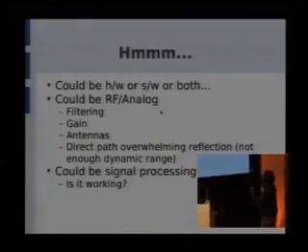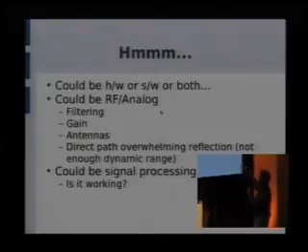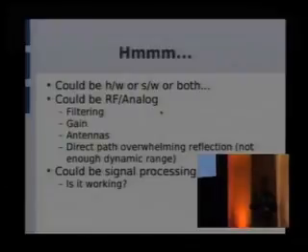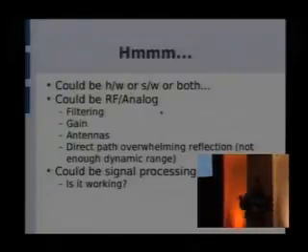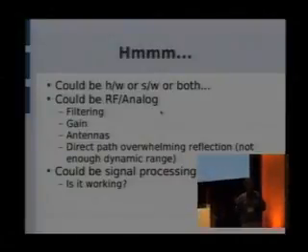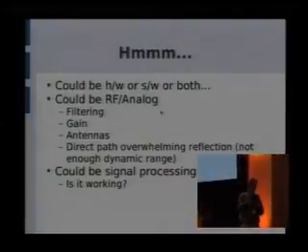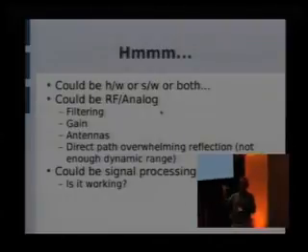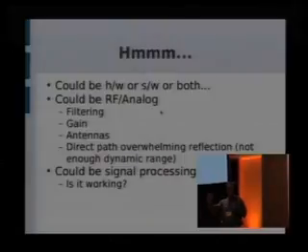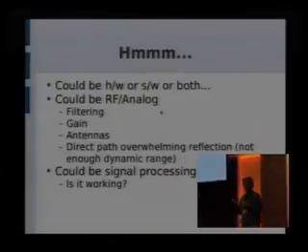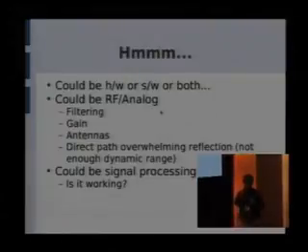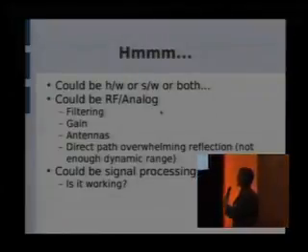So we had some questions, like on the analog section, do we have the proper filtering? In fact, I don't know if I actually showed the block diagram, but in that simplest thing that could possibly work, we left out this piece called the bandpass filtering. It turns out for doing regular FM reception, it works. But part of the problem is that since everything is getting folded in here with no selectivity, you got all these potentially big signals on top of it. So it works okay for the big FM stations because they really still get bounced, but I think what's happening is that the small reflections off the airplanes are getting swamped out.